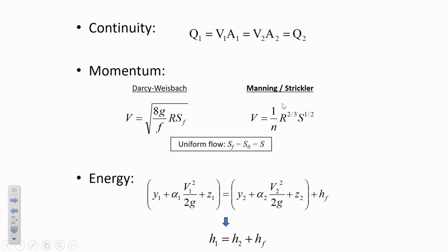So the same thing is true when we apply the Manning's equation, that there would be an N value that's just characteristic of whatever material you've got, and then you don't have to change the N value for flow. And it works well for open channel. Manning's equation doesn't work great in closed conduit flow, but we will use Manning equation for open channel.